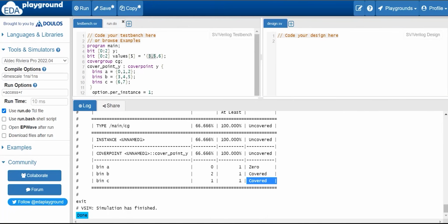If you take the SoC level, when you are writing lakhs of bins, there the hit count will be 10,000 hits, 12,000 hits, 1000 hits, sometimes 5 hits, like that. Whether it is a low count or high count, that should hit. If it is a high count, it will be an advantage. Why? Because more scenarios are covered by using a single bin. So this is how we can analyze the coverage report. Did everyone understand?